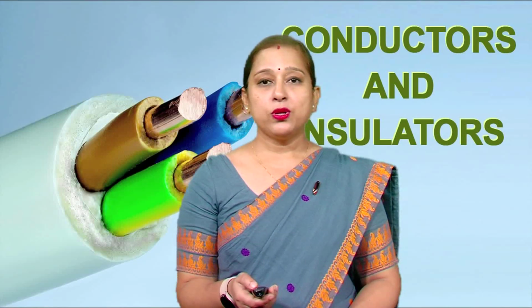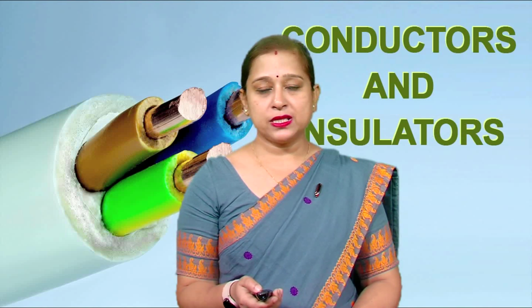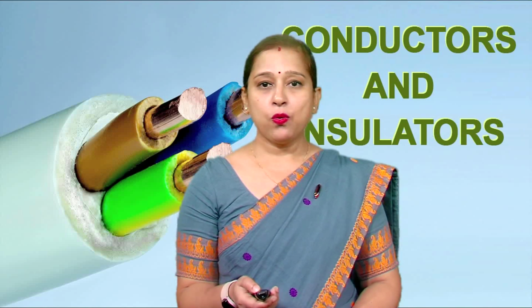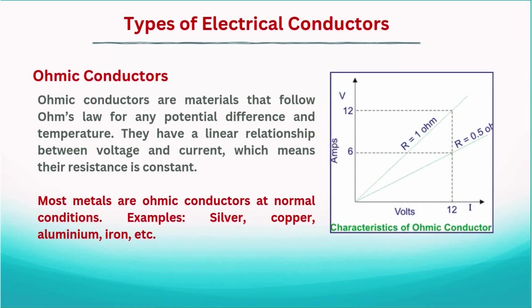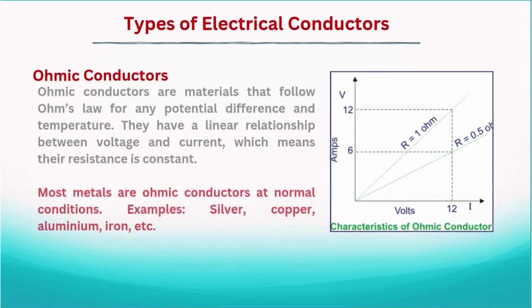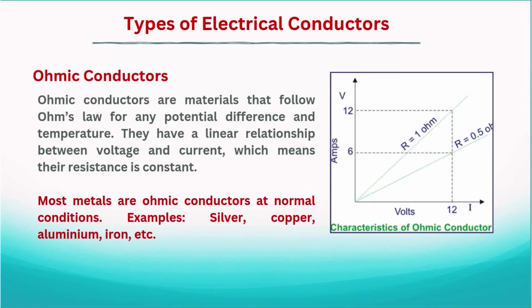Electrical conductors are also categorized by their ohmic response. They can be classified as ohmic and non-ohmic conductors. Ohmic conductors are materials that follow Ohm's law for any potential difference or temperature. They have a linear relationship between voltage and current, which means their resistance is constant. Most metals are ohmic conductors at normal conditions, for example, silver, copper, aluminium, iron, etc.